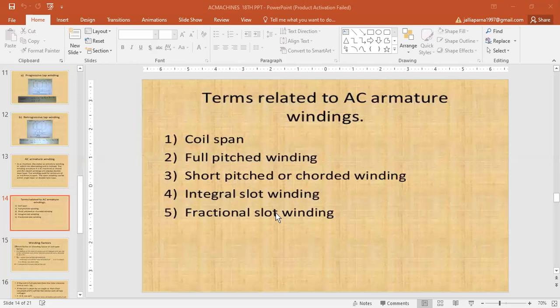However, if the coil pitch is less than one pole pitch, the coil is called a short pitched or fractional pitch coil. In a full pitched coil, the EMFs of the coil sides are in phase, so they add arithmetically. In a short pitched coil, the EMFs of the coil sides are not in phase, and so the resultant EMF in a coil is the vector sum of the induced EMFs, which is less than their arithmetic sum. Therefore, due to short pitch, the induced EMF decreases by a factor called the pitch factor.